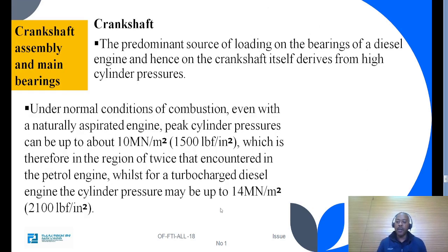Crankshaft assembly and main bearing. Crankshaft. The predominant source of loading on the bearing of a diesel engine, and hence on the crankshaft itself, derives from high cylinder pressure. Under normal conditions of combustion, even in a naturally aspirated engine, peak cylinder pressure can be up to about 10 million Newton per square meter,